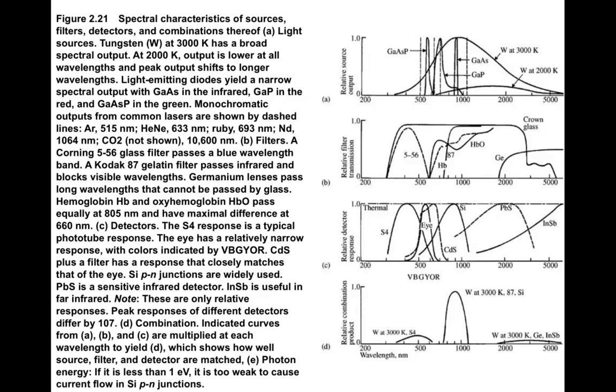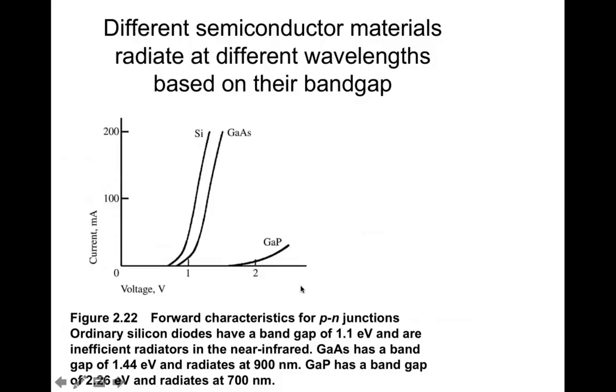So you can see what has to happen is the wavelength of your light source, your transmission media, and your detector all have to have some area in common. And so what you see here on this bottom curve is basically the product of these three curves. So you can see that in silicon, for example, with a tungsten light at 3000 K, you get this kind of combination of light that actually makes it to the detector, is detected, and gives you an output voltage or current.